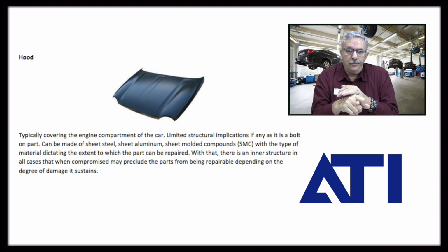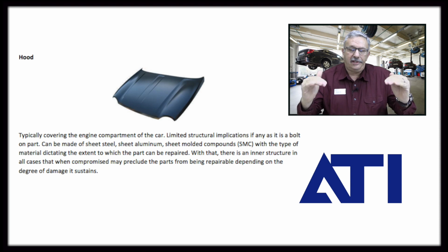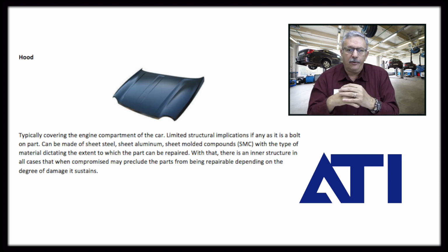So if you've got an aluminum hood and you have to replace the hood hinges, make sure that the hinges you're purchasing are for the aluminum hood. Don't get the steel hinge application. Don't put those with an aluminum hood, and vice versa. You can create some real issues for the driver's compartment if you don't address that properly.